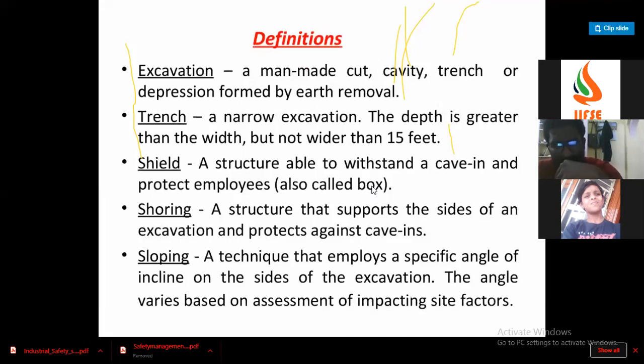Sir, even for excavation, should we do gas testing? Sir, if the excavation is more than 25 feet, or if it is in a closed warehouse or environment, we have to do it. If it is in an open area, there is no need. If the excavation takes a turn after going deep and you cannot see the person, for example, if after some excavation you keep a big pipe, and the person goes inside the pipe to do a weld at the bottom,